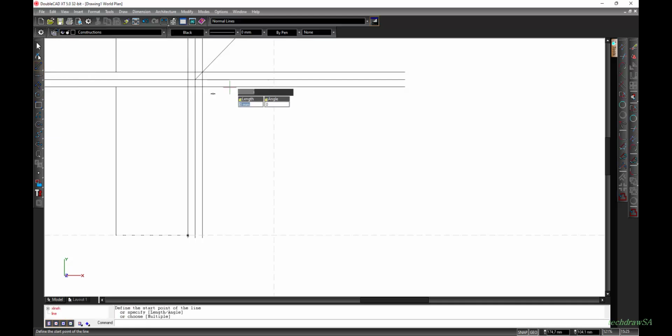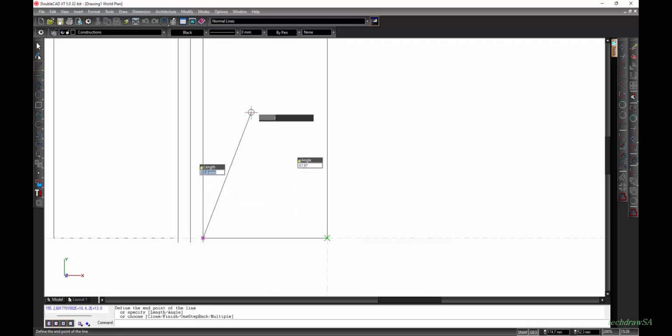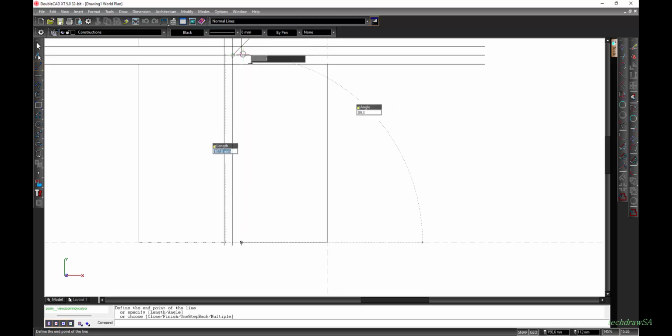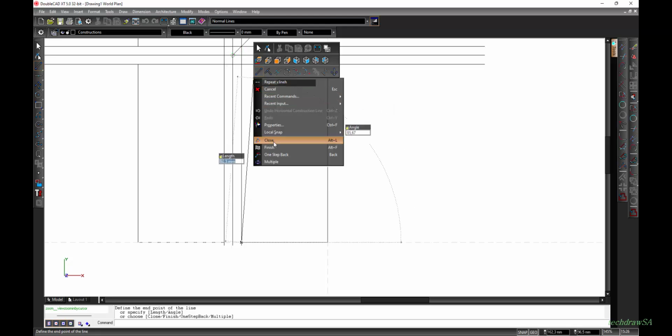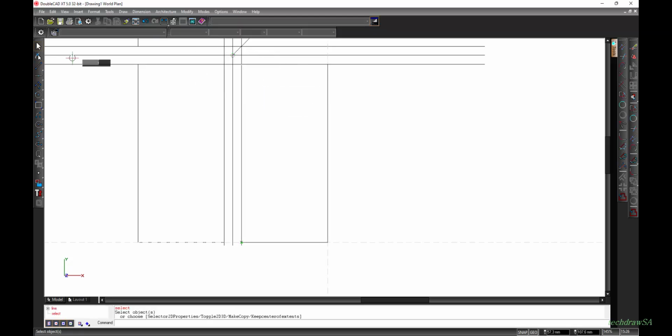If you use the line by line, you're just going to click and drag to the snapping points like that. It will create the polyline itself in this new version, and then you're going to zoom out and come back. You can either right click and say close, or you can just make sure that you click on this point that you started and then escape out of that.